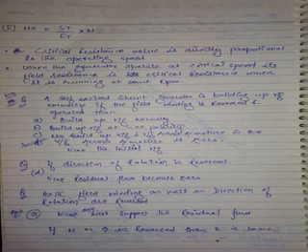The initial shunt field MMF does not assist residual magnetism. Why does it not assist? When the field is not properly connected. Take a problem like this in your notes. Write down: a self-excited shunt generator building up voltage normally.